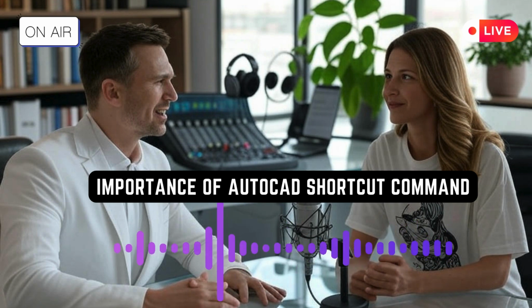Yeah, absolutely. So let's get down to the nitty-gritty. What are some of the essential shortcuts that everybody should know? Okay, well, there are a few that you'll use all the time, like L for line, C for circle. Those are your bread and butter. Then you've got M for move, CO for copy, and E for erase. These are your everyday workhorses. They're going to save you tons of time on just basic tasks.